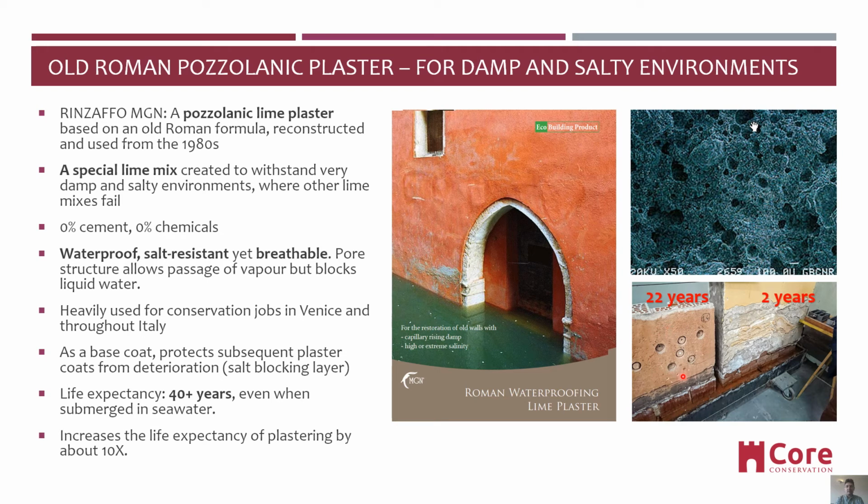And the pink or red color plaster applied on top of this base coat is intact after 22 years. So we can see a bit of salt crystallization at the boundary, but in fact it's intact, and they have been taking lab tests to see that it did not debond. That's where these drill holes are. And on the other hand, without the base coat, the plaster has completely degraded after 2 years. So just a case in point.